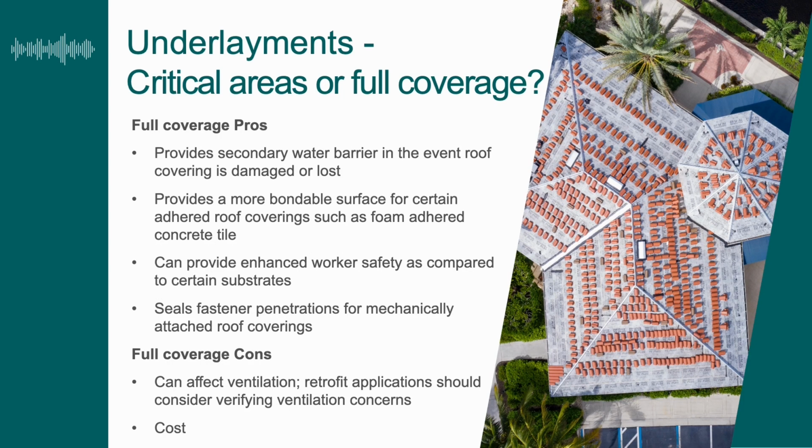So some of the disadvantages of going with a self-adhered underlayment over the entire deck and sealing the deck are, obviously, cost, because you're talking about a premium product being applied over the entire roof deck. So there's that disadvantage, and consideration must be given to ventilation, right? Because when you're using a self-adhered underlayment over the entire roof deck, it effectively acts as a vapor barrier. So sometimes you have to consider, do you have adequate attic ventilation? Or if not, you can install an anchor sheet on top of the roof deck before you install your self-adhered underlayment, so you have additional ventilation and don't have moisture trapped in the roof deck.